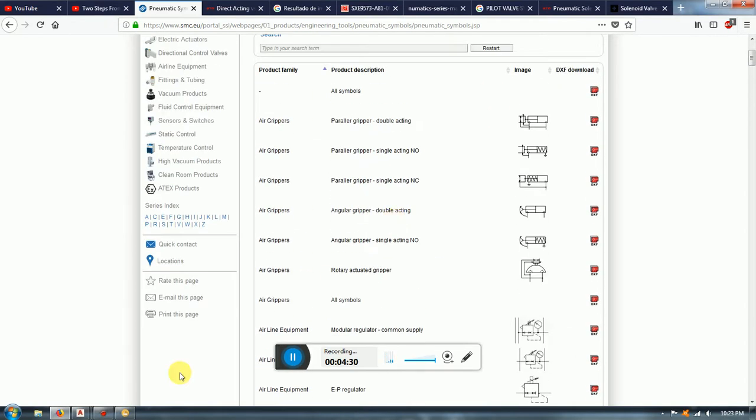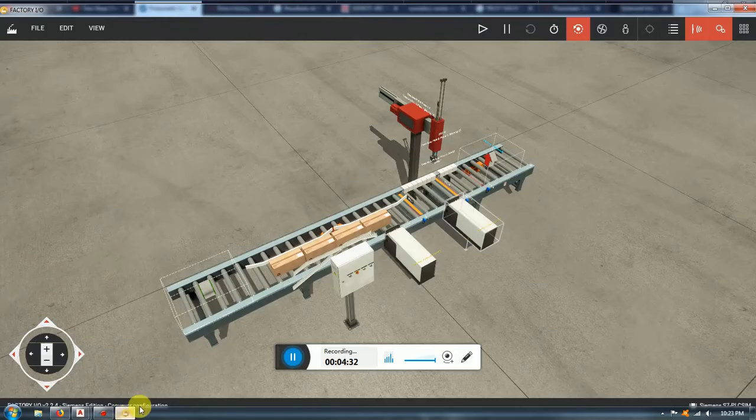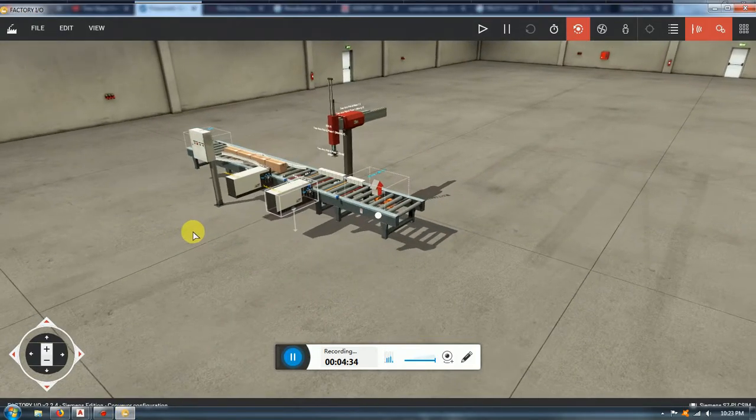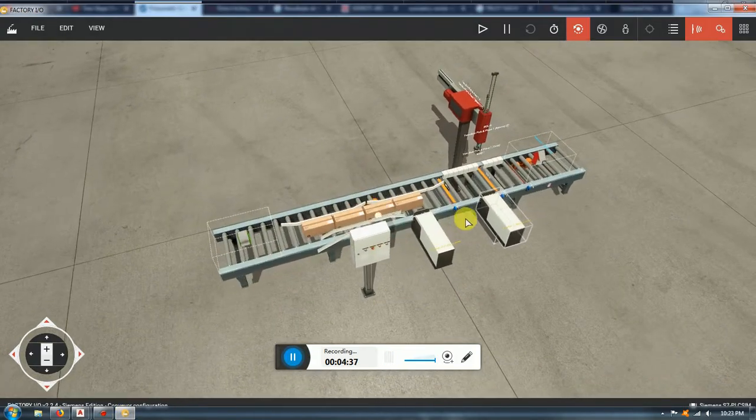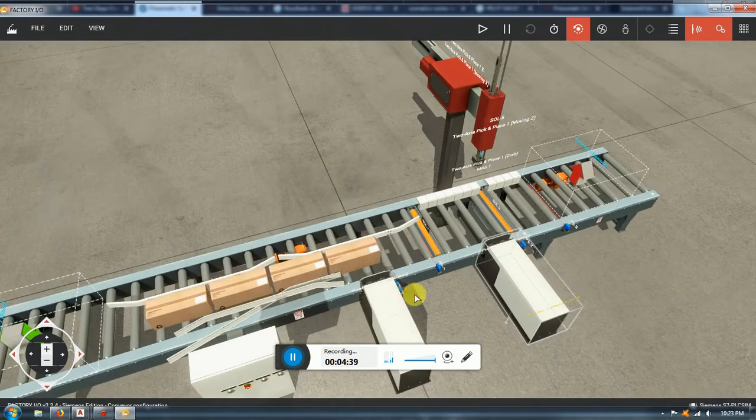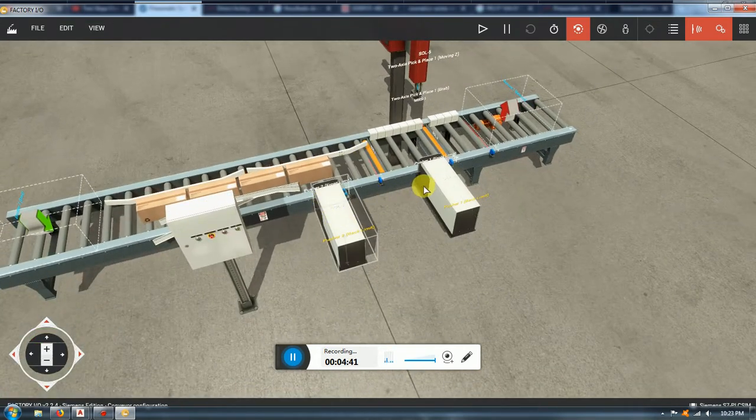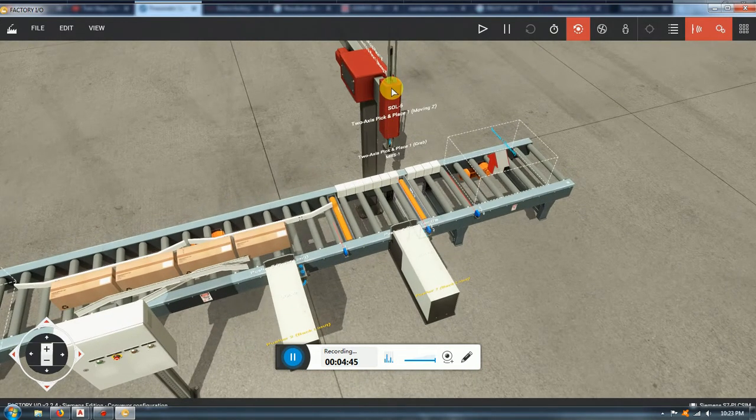So we're going to start with, remember, we want to pretty much do a diagram of this machine, okay? What does it have? Well, it has the two clamps, it has the two stops, and it has the main thruster, which is going to be a stamper. Okay, so that is a maximum of 5 solenoid valves. What more stuff do you need? In this case, pretty much nothing. In other options, we're going to have different extras.